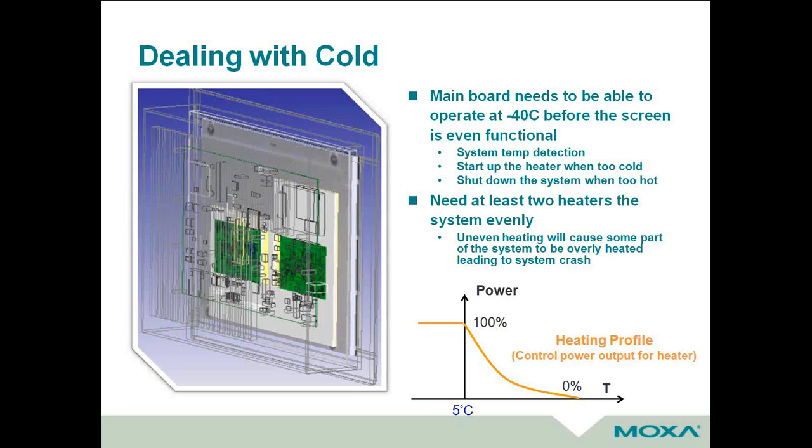It's adaptive, it's dynamic. It's not just turning on the heater and then turning off. That's really important for an HMI that has to be placed in, say, a drilling rig in Alberta, Canada, or Alaska for that matter. And a way to address that too, from a simple design feature, is that it generally should have 2 heaters inside so that the heat can be evenly dispersed in the unit.